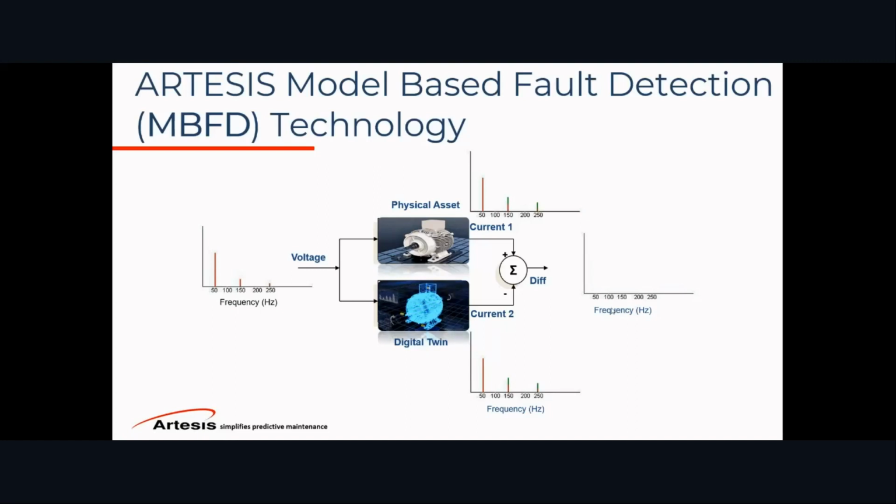What I mean by that is, if you have harmonics on your supply voltage, which is not a clean signal to the motor itself, that can cause, for instance, a voltage unbalance, or your compensation is not right. You will see a dirty power here, which can then vibrate the motor itself, or in the long run, it can cause stutter issues or other issues on the motor itself.